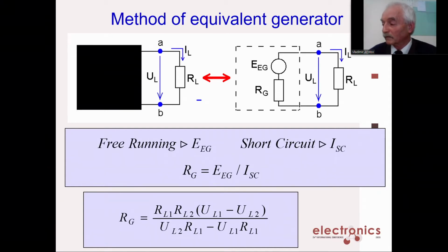The appearance of the input pulse causes a reverse current through the diode, leading to dissipation of the accumulated charge. At the end of the latter, the resistance of the diode rapidly increases and practically all the input voltage is applied to the load. The appearance of the input pulse and the diode switching is accompanied by transients in the circuit.